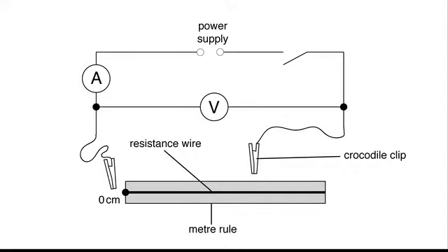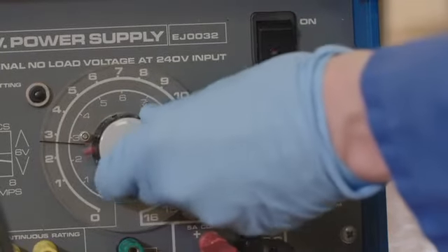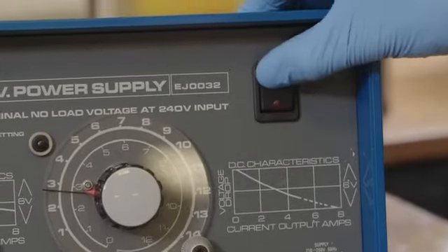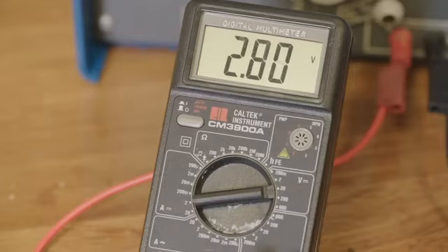Before the circuit is switched on, check carefully that it is set up as shown in the diagram. Make sure a results table is ready to record the data. After turning on the power, the readings from the ammeter and voltmeter should be recorded.